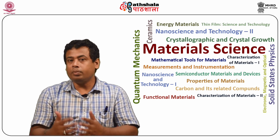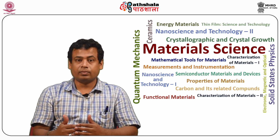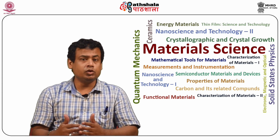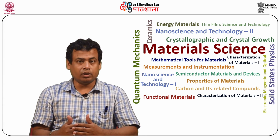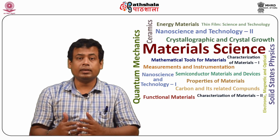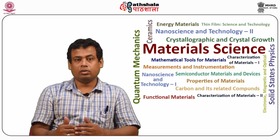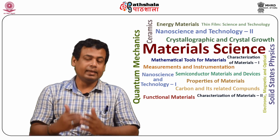In the electron optics, the refractive index changes continuously and electrons interact with each other. Electron lenses are used to converge the electron beam. Magnetic lenses are used to twist the beam, and electrostatic optics has larger aberrations than magnetic. Feature sizes at tens of nanometers could be produced using electron beam lithography.